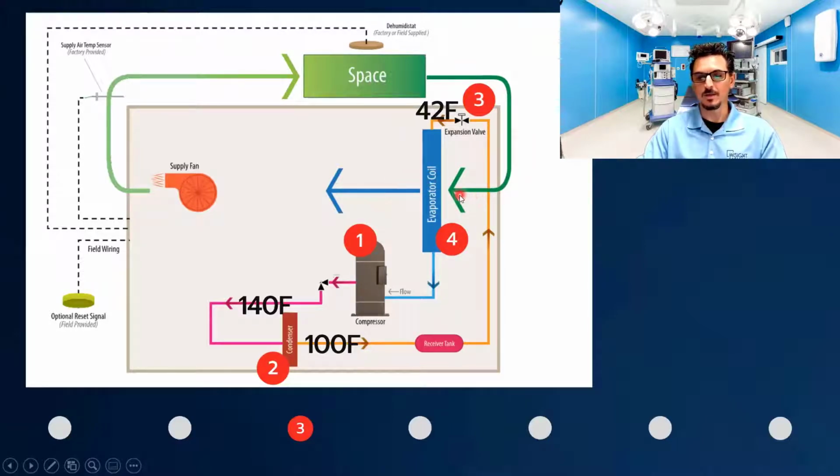That's where the whole air conditioning refrigeration effect takes place. The ability to change state from a liquid to a gas, that's the whole purpose of the refrigeration cycle. So it absorbs the heat and boils off, leaving at approximately the same temperature, just a different state, and then goes into the compressor. Okay? So that's your basic refrigeration cycle, 4 components, pretty common in all refrigeration cycles.